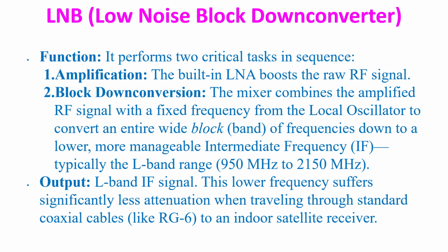LNB, low noise block down converter. What it contains: an LNA, a local oscillator, a mixer, and an intermediate frequency filter amplifier integrated into a single weatherproof housing. It performs two critical tasks in sequence. Amplification: the built-in LNA boosts the raw RF signal.